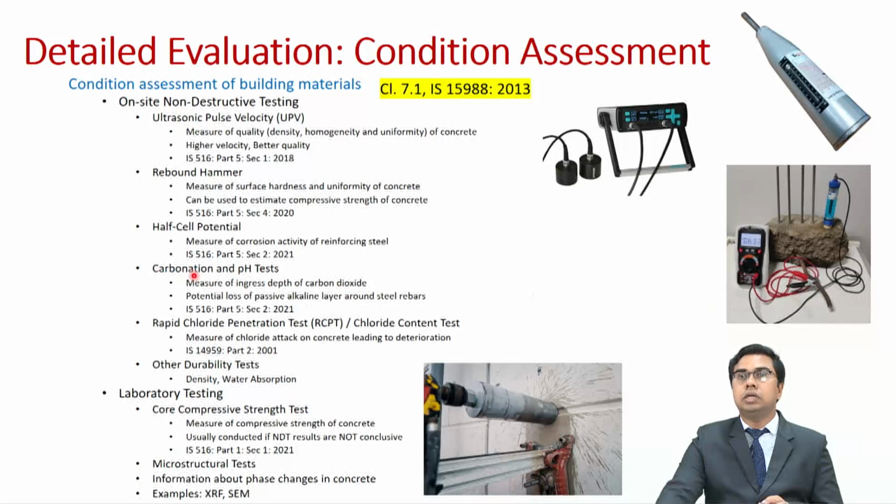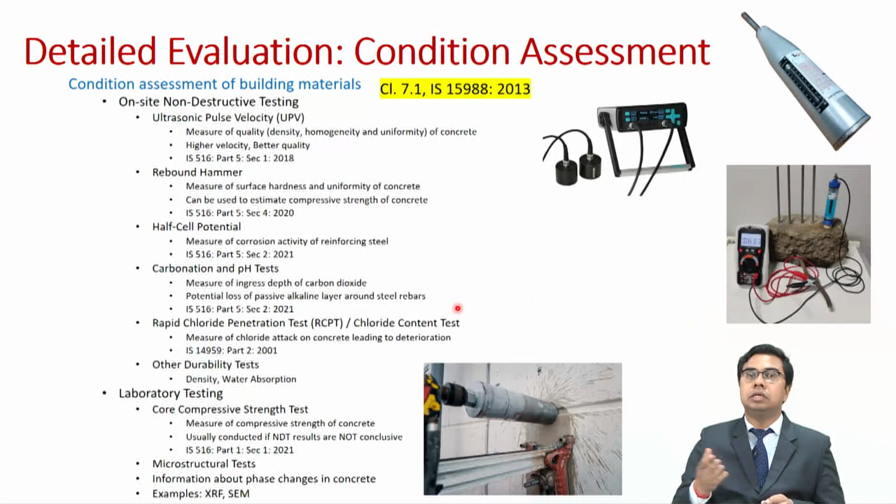Then you can have more tests which are related to durability of concrete, such as carbonation and pH tests. This gives you a measure of ingress depth of carbon dioxide and a potential loss of the passive alkaline layer around the steel rebars. Let us say that the carbonation depth is 10 millimeters. Then we can say that the reinforced concrete is still safe because the carbonation has not reached the steel, because carbonation leads to loss of passive alkaline layer around the steel rebars that can lead to corrosion.